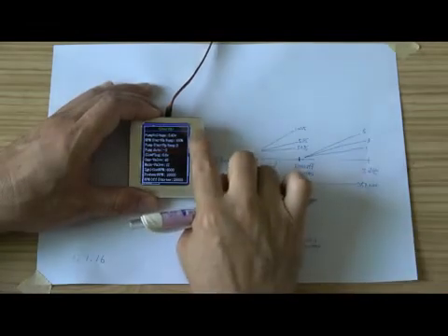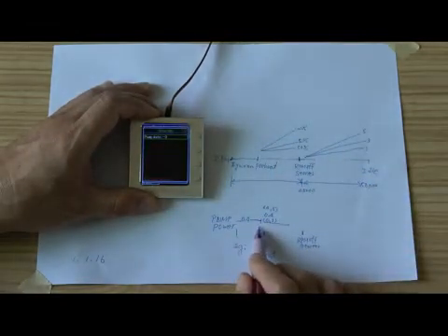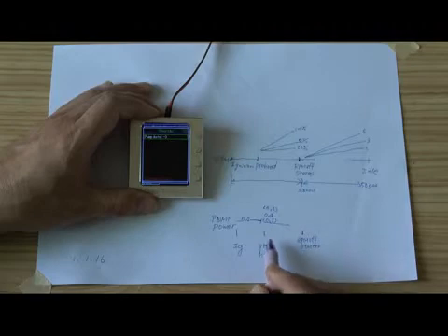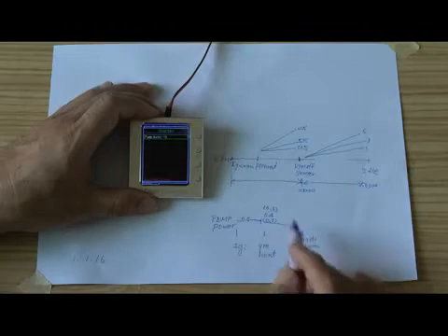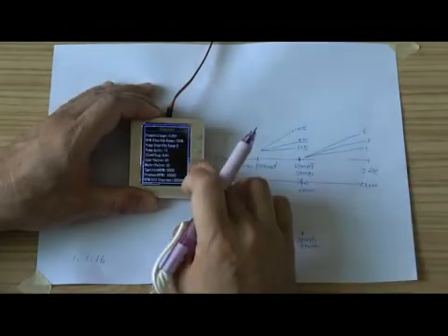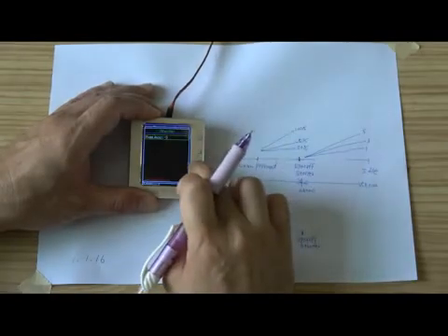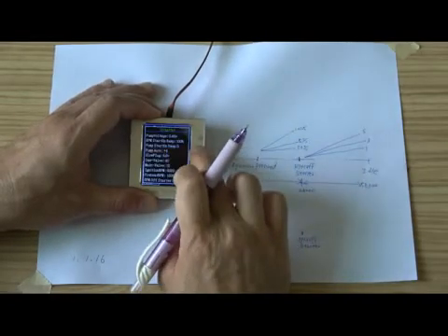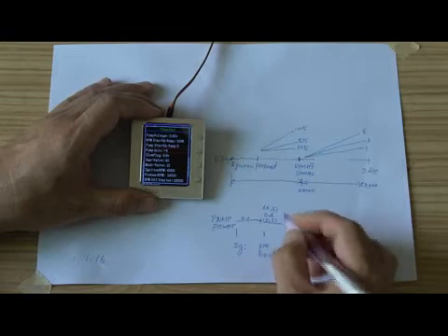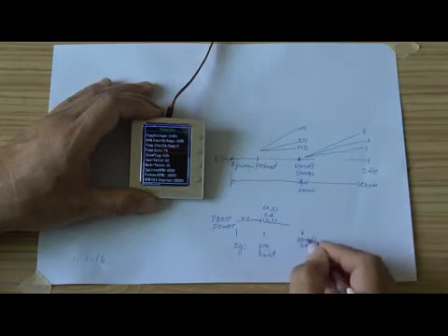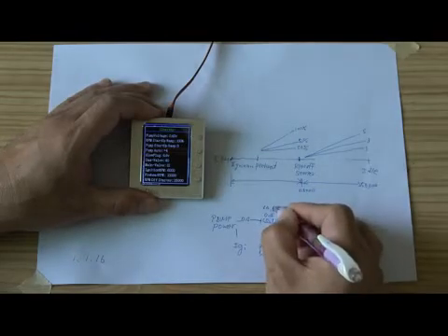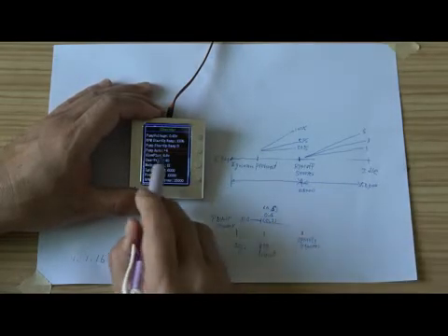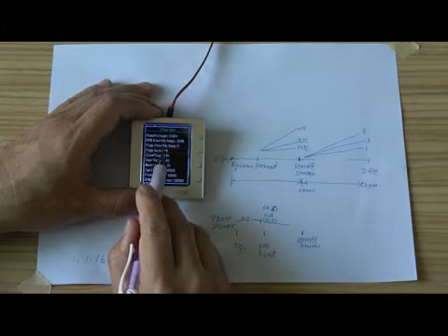If you find after ignition is successful and into preheat that the temp is going down, that means you need to increase fuel. You must increase fuel during preheat to the RPM of the starter, maybe 0.5. You plus this parameter.